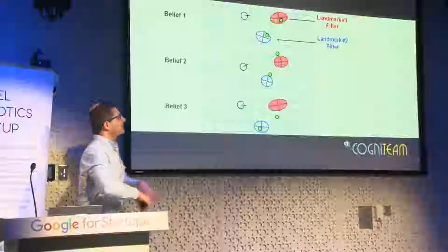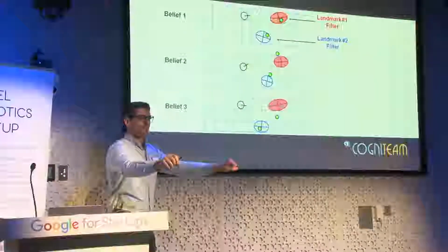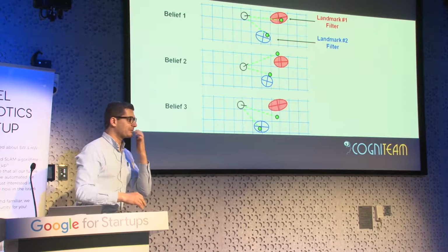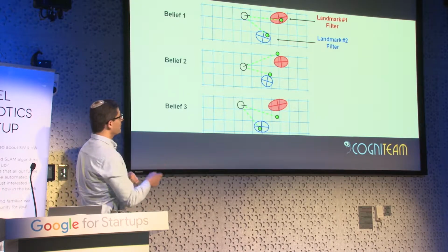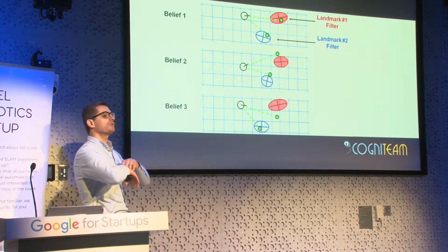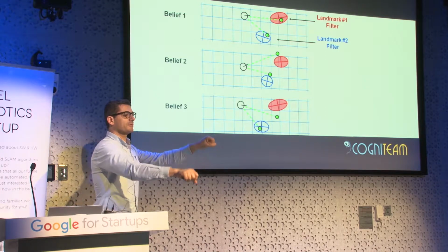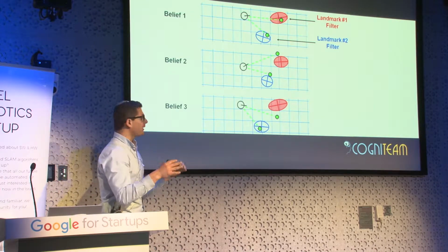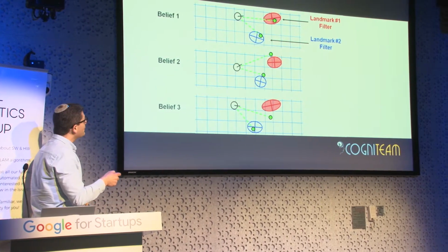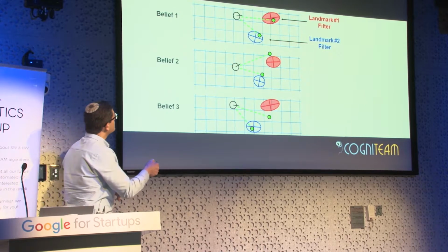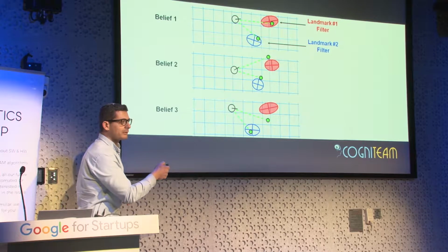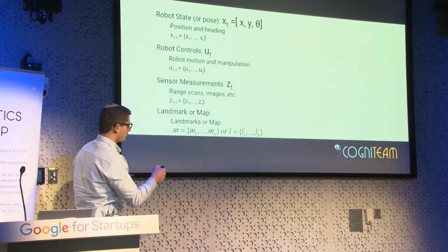Then it opens its sensors and starts to recognize landmarks, obstacles, something that you saw in the previous step. In this simple example, we will assume we have two sensors, let's say two sonars, and now it feels obstacles. You look at the map, and it sees that it's correlated here to its location. So we are accurate. This is a good expectation of where I am located.